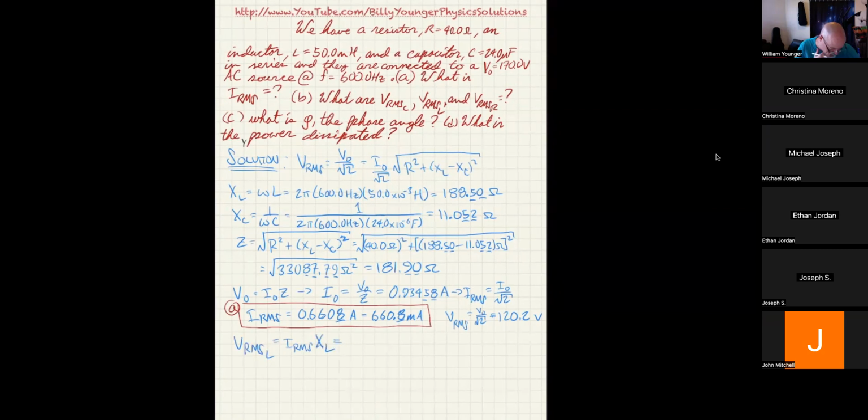We know XL is 188.5, so I'm going to go 0.6608 amps times 188.50 ohms, and that's going to give us 124.56.